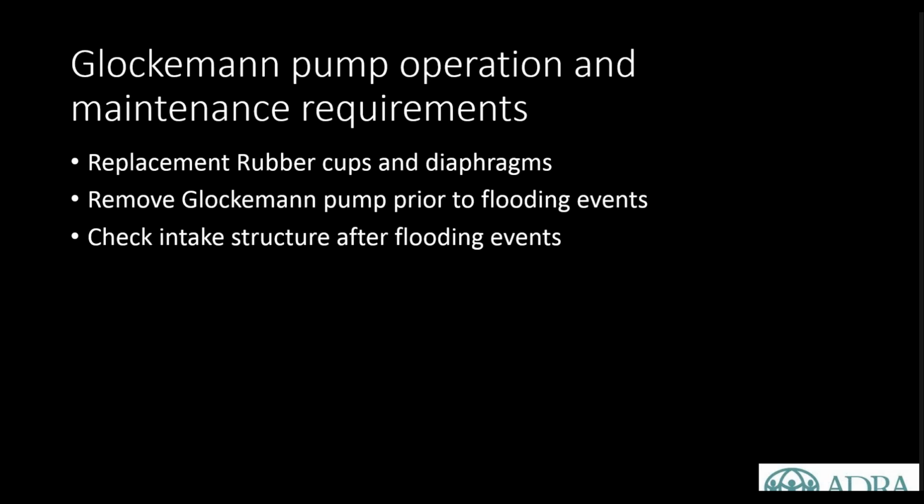The other thing to consider with these pumps is that any air in the delivery line will stop the flow. So if you've got a delivery line which is on a constant incline, that's good. If you've got a delivery line which goes up, then down, then up again to the tank, that's going to create problems, and you'd have to consider some sort of air release valve if you've got a change in grade on that delivery pipe. Okay, good. Thank you.